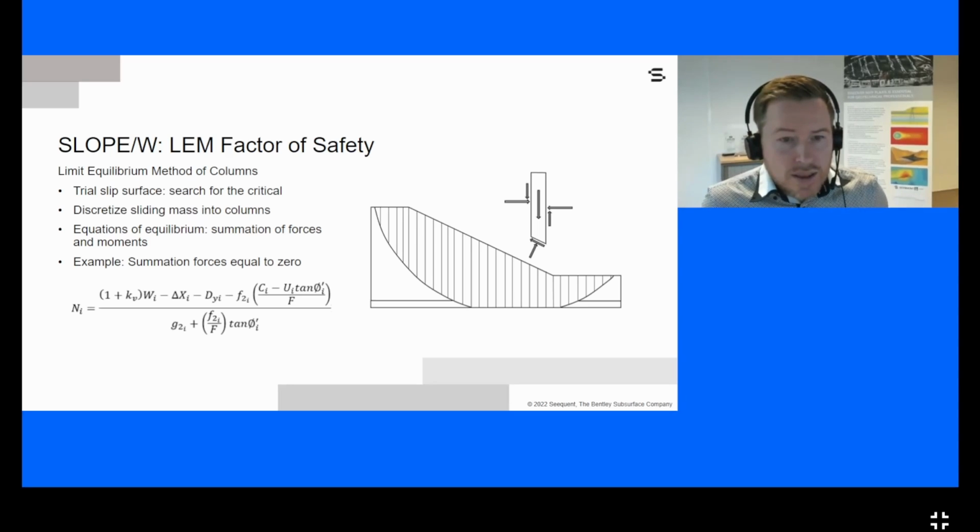What's good to note about that is that we also take the factor of safety F into account in this equation to have a state of limiting equilibrium. And this F, we can calculate based on the available shear strength over the mobilized shear strength. And then we can, of course, rearrange it such that we can use the mobilized shear strength, Sm, as the shear strength divided by the factor of safety.